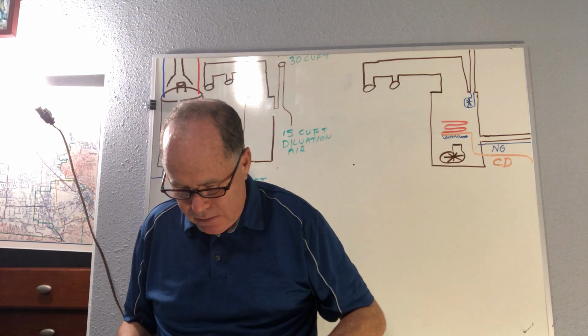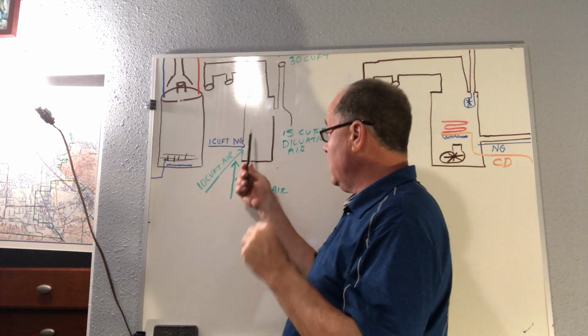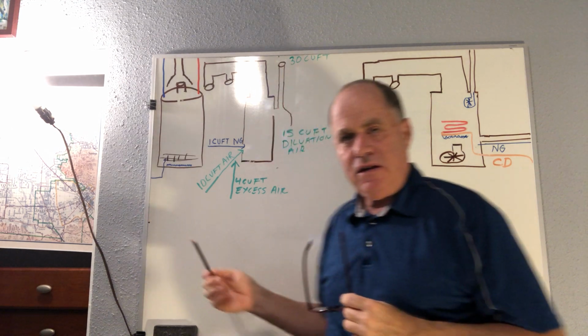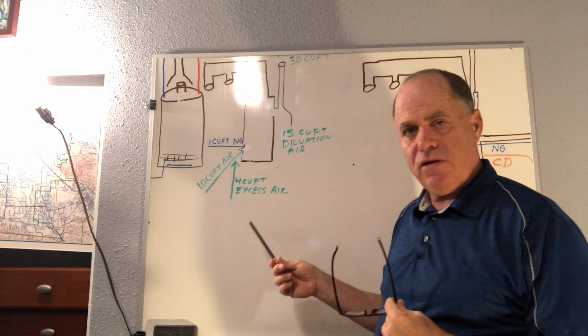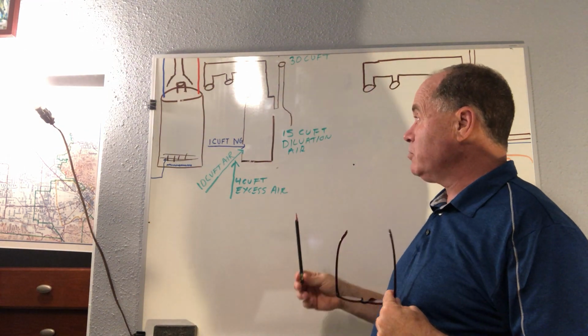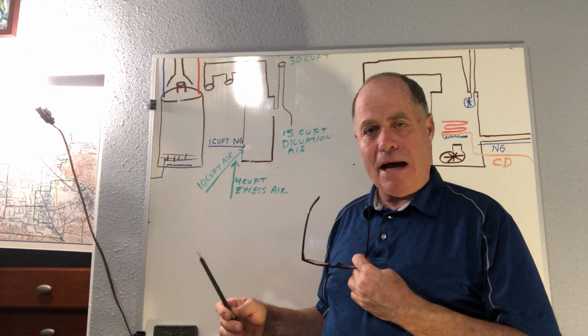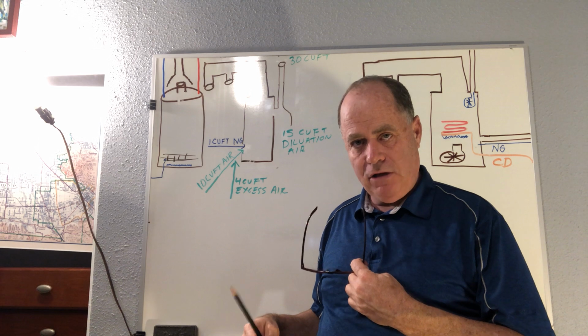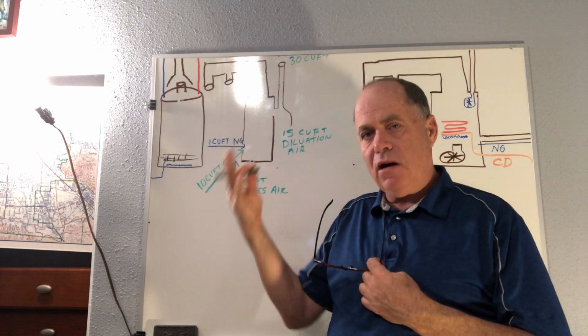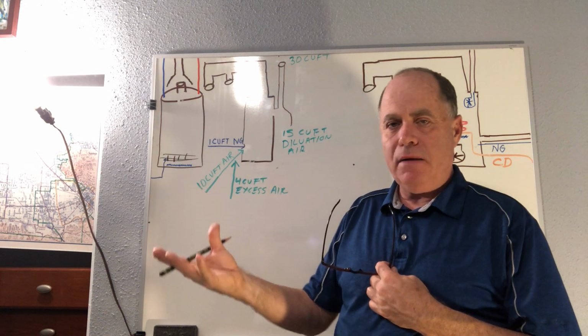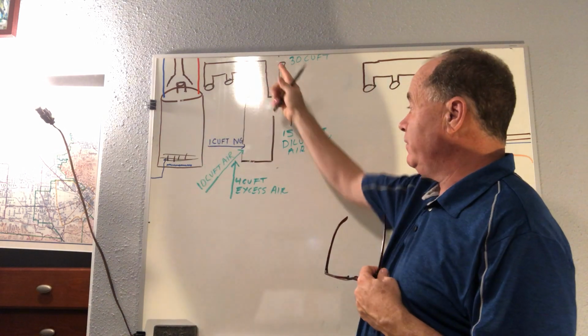All right. Let's get on with this furnace. They show you in the chapter this picture that I drew of a natural draft type of furnace that doesn't have a power venter or a combustion blower, where it's just relying on the natural warming of the byproducts of combustion to go out the flue or chimney pipe.